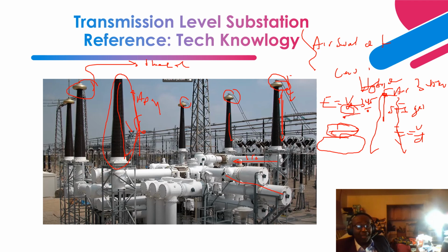There's a transmission line coming in to connect to this connection over here. We're stretching the distance, D. As we increase this distance, the electric field decreases. That's how we are able to protect the porcelain insulation from damage, and also prevent corona action due to the breakdown of the surrounding insulating air, due to high electric field.